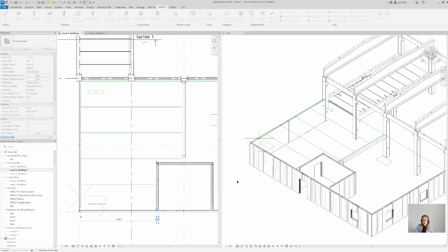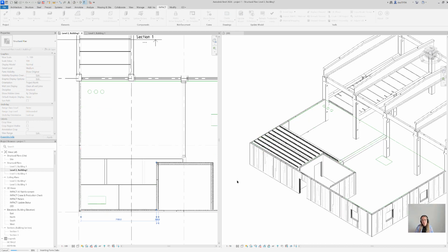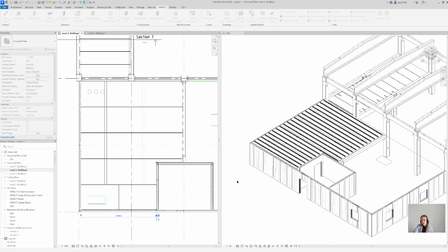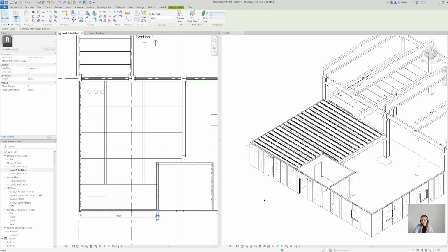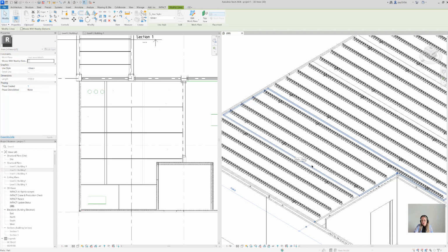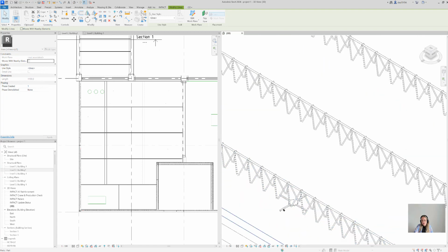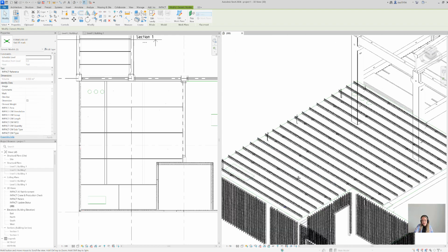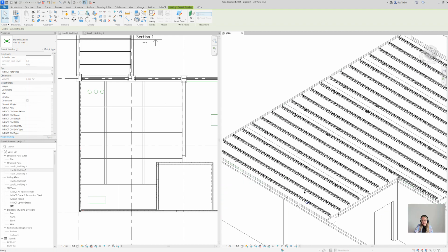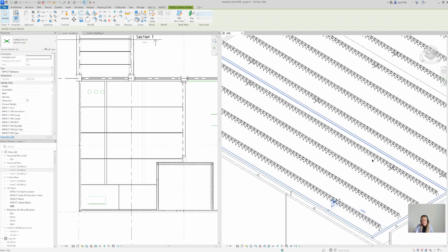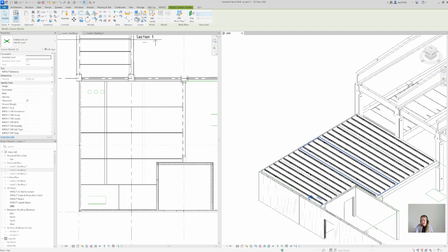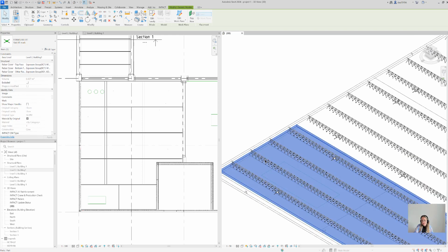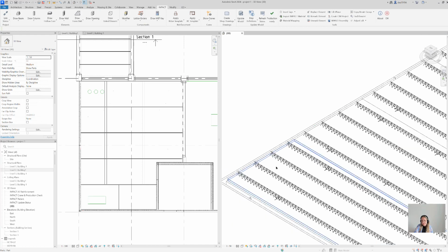Okay, let's see how my form slabs are looking. If I go and say draw, Impact Revit is going to insert my form slabs for me. And let's see what we have in here. We actually have some, we call them lifting symbols, automatically inserted here on the form slab so that they can lift in the girders just on this point. This is the definition. We define the family that we use, this lattice girder, right? And we define the spacing.